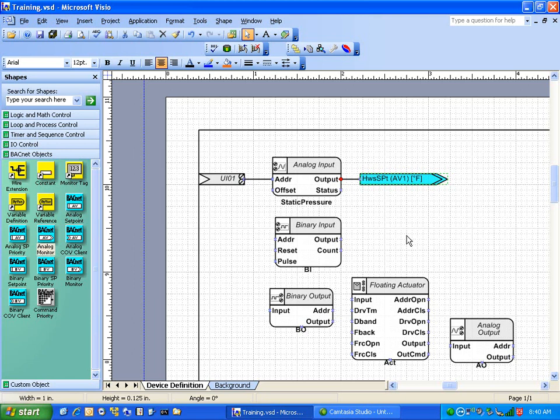The only other thing is BACnet has this thing called peer-to-peer. And what we're finding out is it's exclusively through just our own controllers that you can do peer-to-peer type communication. So if I need to share this to another controller, and I'm looking for something speedier than sending this up to a UNC and then back down to another controller, where we know you're going to come into a bit of a timing issue.